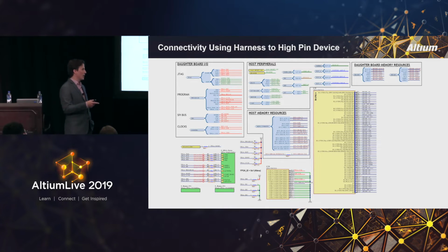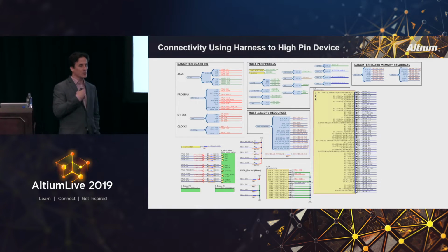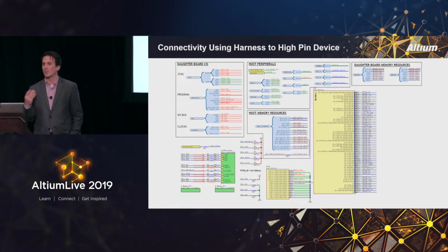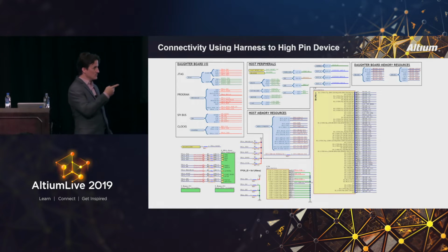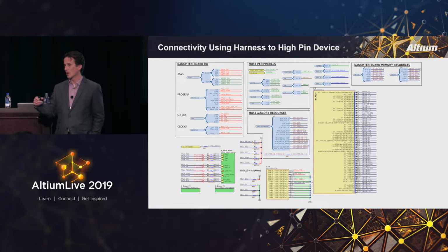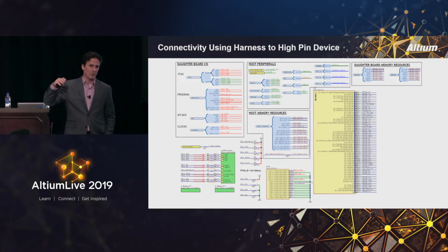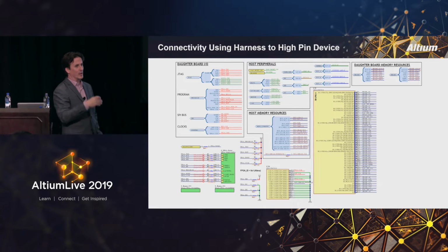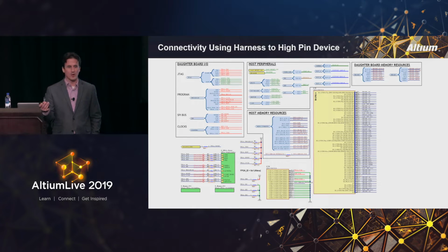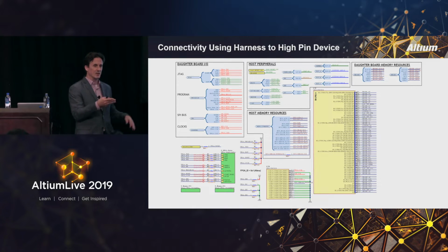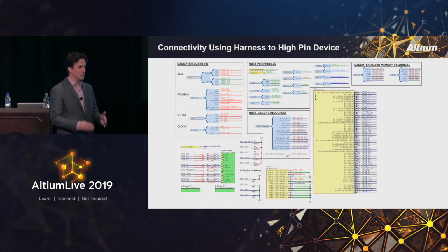Not only does it allow, from an electrical engineer's perspective, me to make changes if I remux a pin for a different function. But when we're laying out the PCB and I'm backed into a corner and I see that 5 pins that are more on that side of the IC are open, now I can readily change, assuming it's allowed by the function of that pin. Now there's at least a path to changing to a pin that's easier. Yeah, it definitely greatly simplifies the escapes.